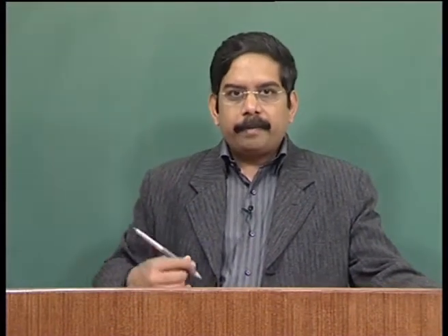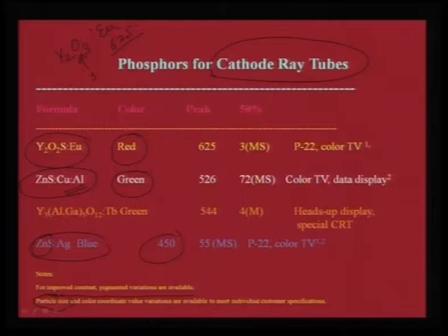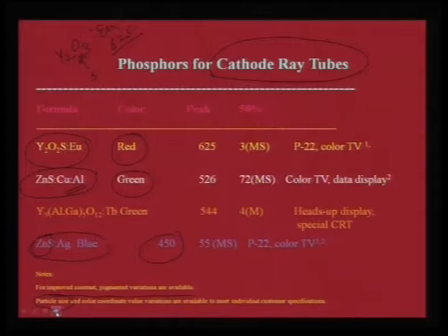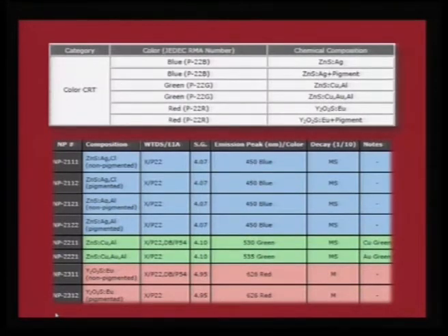Therefore, if you want to make such sleek and very narrow width of these phosphor stripes, then the particle size of the starting material is important, because you need to make a blend and then you need to burn it carefully to make such very sharp strands of phosphor. Therefore, particle size becomes a very unique issue, and it is preferred by different customers who have different technology to deposit this phosphor on the glass slide.